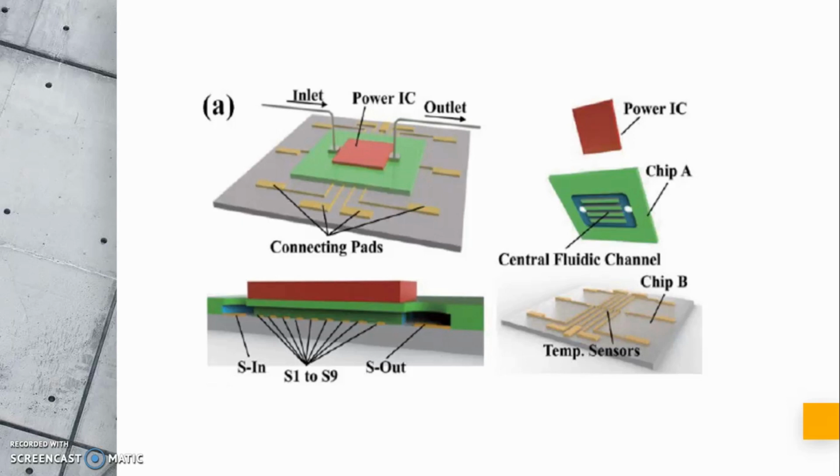A thin film-based resistor is employed as a temperature sensor because of its high sensitivity and stability. The temperature coefficient of resistance of the annealed PT thin film remains stable at elevated temperatures. To precisely measure the resistance, all sensors are wire connected, eliminating the effect of parasitic resistance of the connection wires.